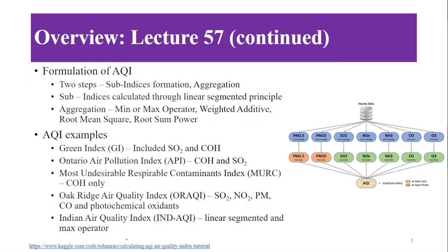Finally, the Indian Air Quality Index was discussed, which uses the linear segmented principle for the calculation of the sub-indices, and then for the aggregation it uses the maximum operator. For aggregation, different types of operators or methods can be used. India uses the maximum operator method. It can also be in weighted additive form, root mean square form, or root mean sum form.